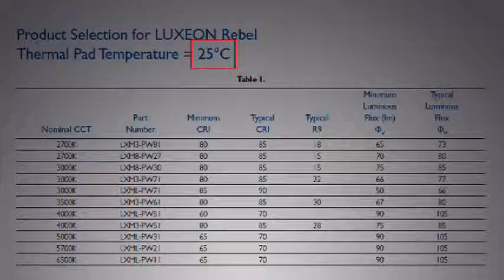So what you care about is really the amount of usable light that the LED emits within the application's operating conditions. The light output degradation as a function of junction temperature is known as the hot-cold factor. In other words, it's the ratio of light output at a higher junction temperature, 100 degrees C for example, to the light output at a junction temperature of 25 degrees C.